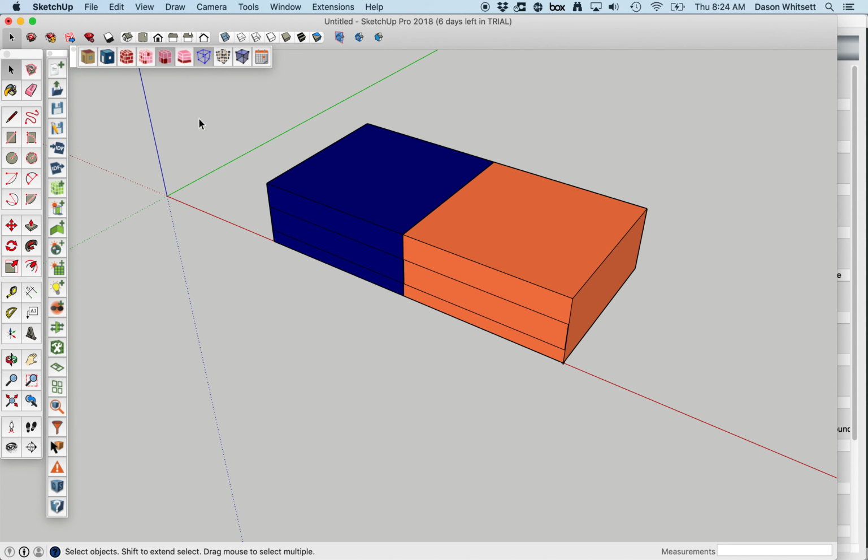For daylighting to work in EnergyPlus, you must first have electric lighting set up for your zone. Once you put in the appropriate objects, when you run the simulation, EnergyPlus will calculate the illuminance from natural lighting in the space, compare that to the required illuminance from the electric lighting, and reduce the lighting output accordingly based on the parameters that you've set up with your daylighting controls.